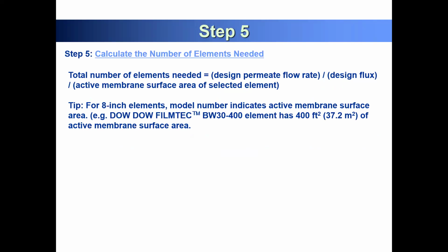Calculate the number of elements needed. If we know your average water flux, 40 LMH or 30 LMH, you can also calculate the total number of elements needed. So for the 8-inch, 40-inch size element, the total can be calculated from this simple formula. Total number of elements needed is design permeate flow rate